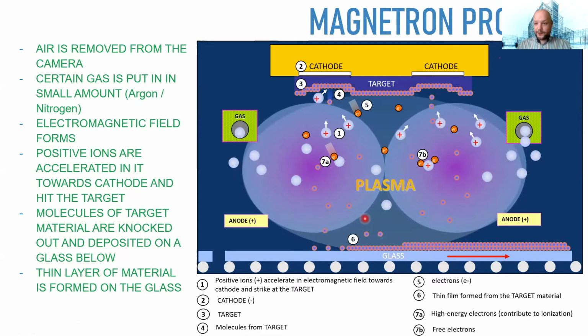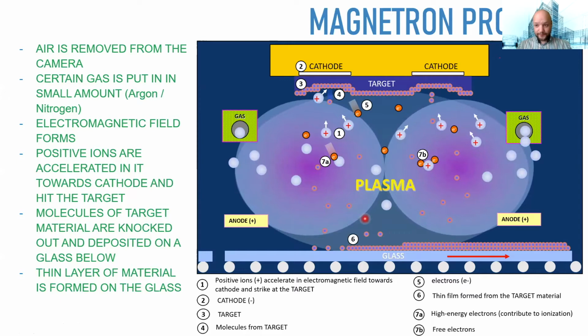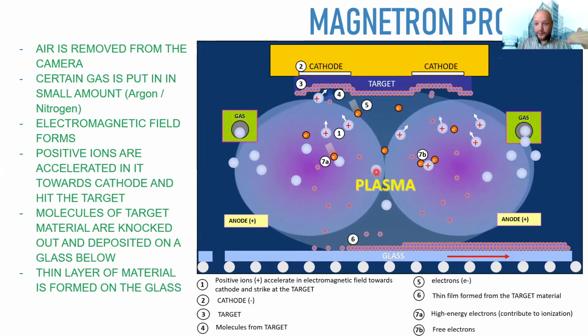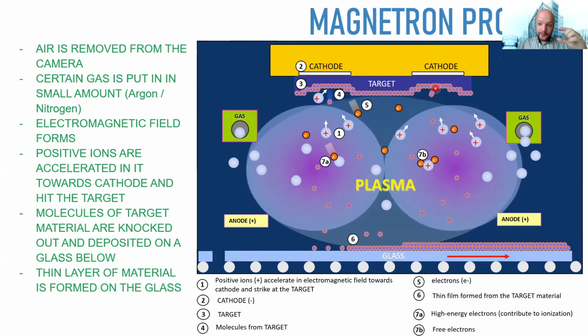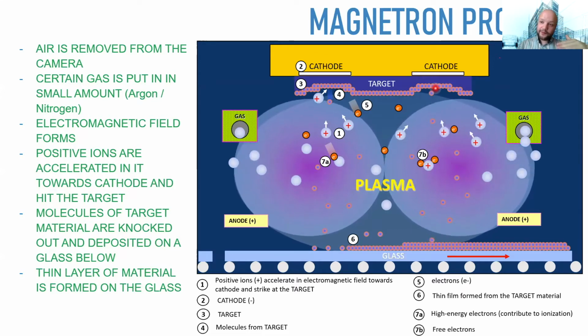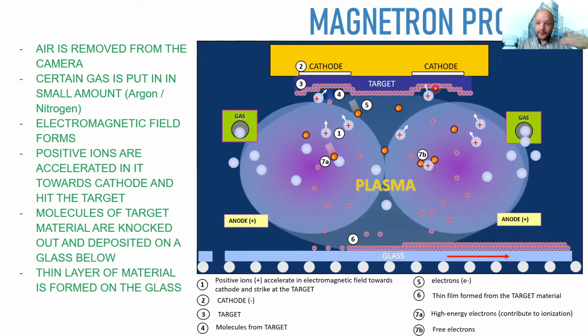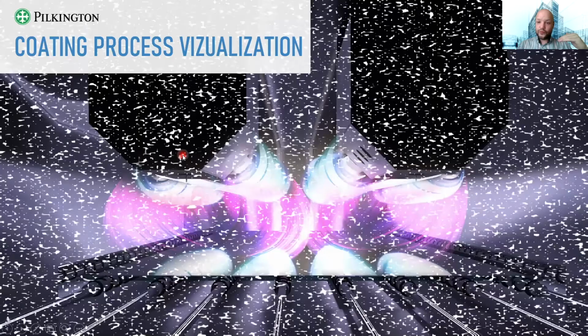Coating machine usually consists of many chambers. Sometimes it's more than 20. And this is used to turn them on and off to produce different types of coatings in a single coating campaign. And with the speed of the glass and the energy in there, you can regulate the thickness of the layer individually. So as a result of the magnetron process, we can have a multi-layered coating with different thickness and different materials on the glass. What it allows us to do.